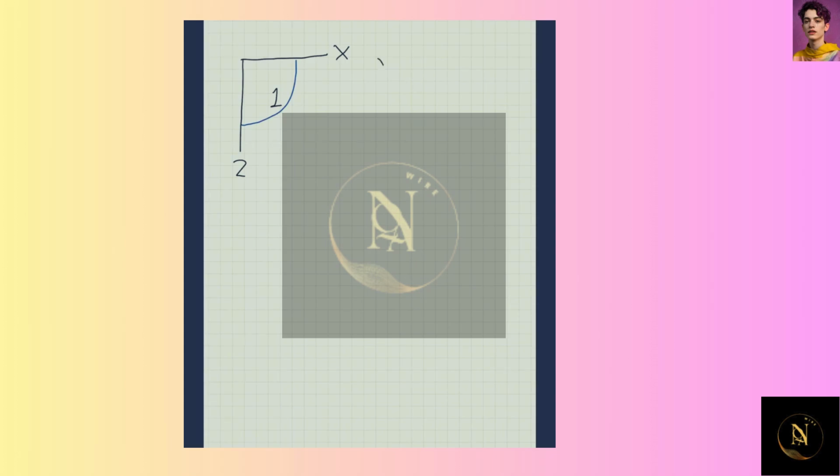So looking at this xz plane and the curved piece, we can find the centroid by taking the integral of a point on the curved piece of wire times a change in length of that wire and integrating across the entire wire over the integral of the change in length.